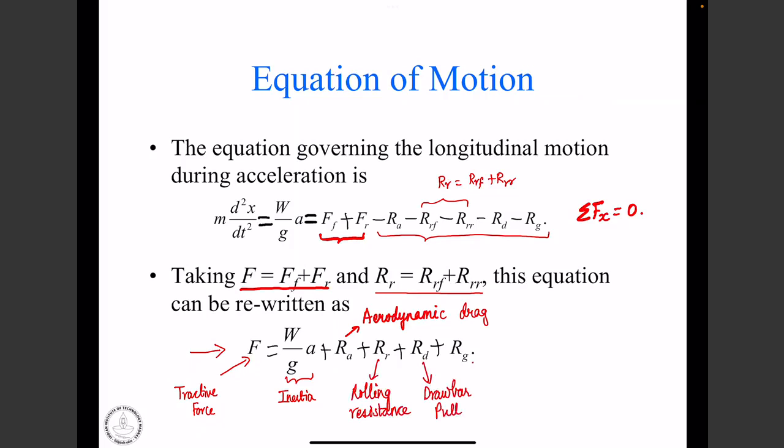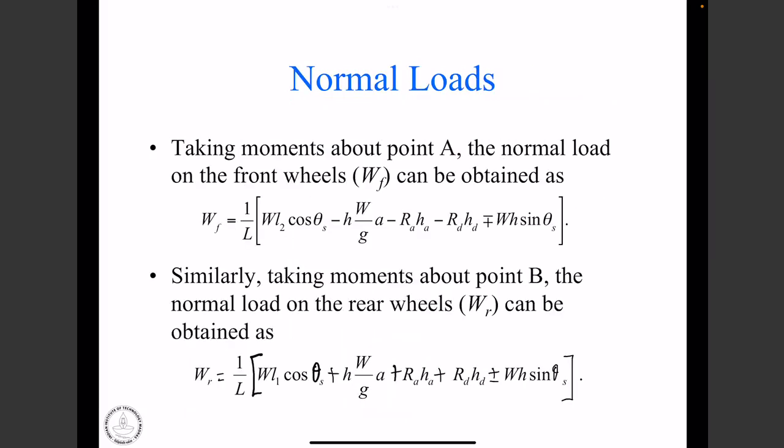And finally, we have the grade resistance. In case the vehicle is going up a grade, the corresponding mg sin theta component also needs to be overcome. So these are the various loads that the powertrain needs to overcome, and when we sum them, that is the tractive force that should be provided by the powertrain.